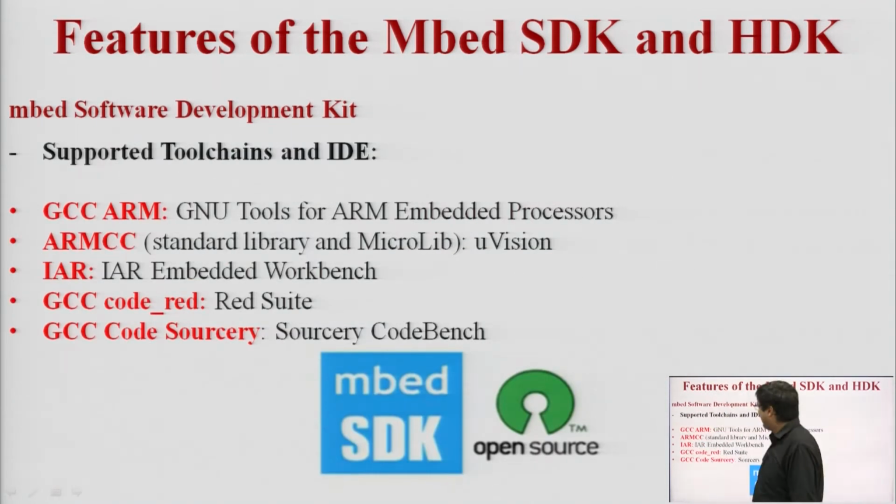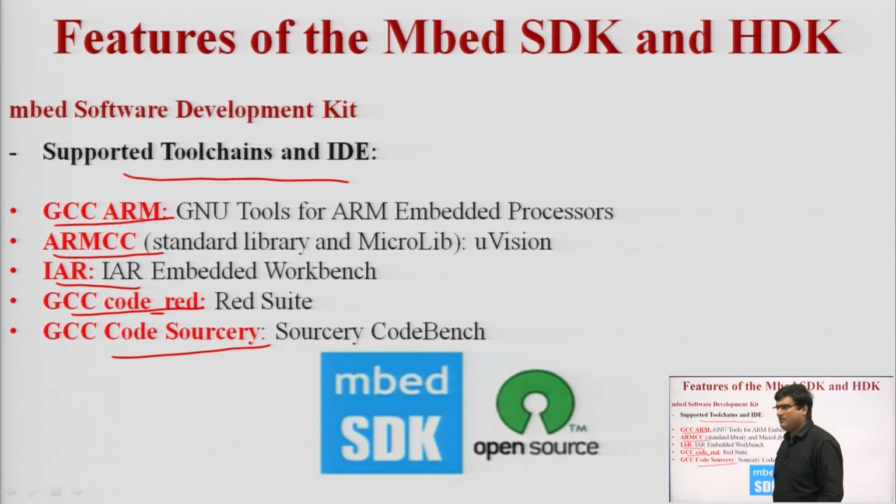Under this topic, Mbed software development kit, we will see the supported tool chains and IDE. These are the supported tool chains: GCC ARM, ARM CC, IAR, GCC Code Red, GCC CodeSourcery. So basically, this is a theory. For implementation, you need to go to Google and check the Mbed platform. After that, you will be able to understand the things in a better way.